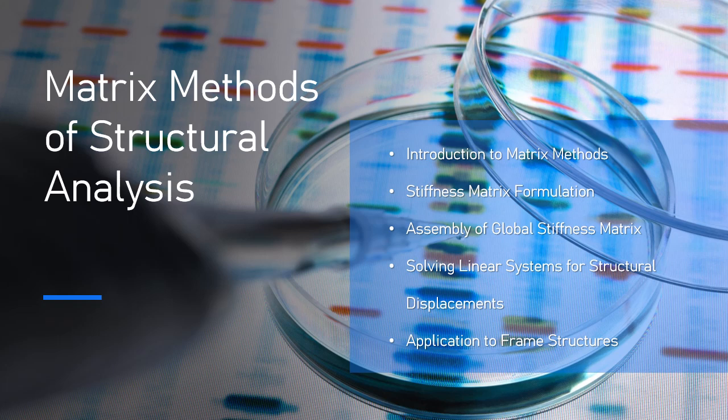3.4. Post-solution analysis. After solving for the displacements, you can calculate internal forces and moments in the structure. Use the displacement vector and the stiffness matrix K to compute the internal forces and moments in each element: F_internal = K·Q. Deformations and stresses. Based on the displacements and internal forces, you can calculate deformations, strain, and stresses in the structural elements.